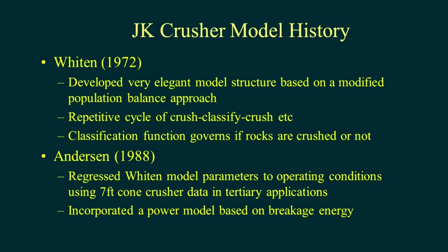In JKSimMet, you'll find that the Anderson-Whiten crusher model is the one that's normally used. And Jan Anderson was a master's student when I was, and I shared an office with him. So I know that model inside out because he developed it. It was fitted and validated using a database of 7-foot cone crushers, and it works very well for 7-foot cone crushers. And he also put in a power model.